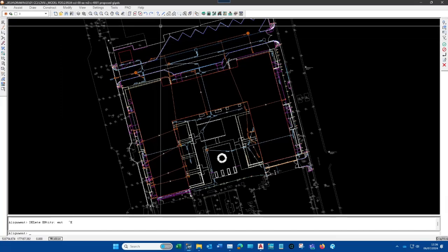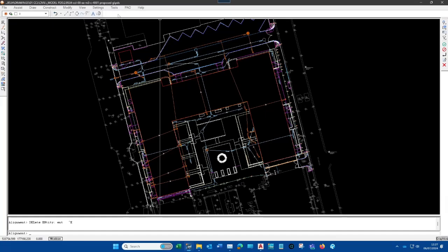So let's try it again. Here we have draw. It's got the little triangle in the bottom right corner. You click on draw, and the standard toolbar is replaced by the draw toolbar. Click on the curved arrow, go back up to the main, go to construct. There, the standard toolbar is replaced by the construct toolbar. Go back up to the main.